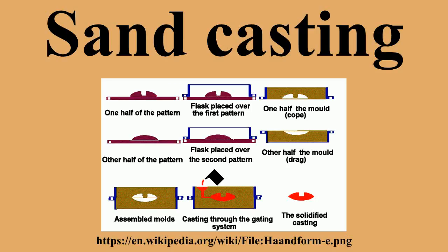In addition to the sand, a suitable bonding agent is mixed or occurs with the sand. The mixture is moistened, typically with water, but sometimes with other substances, to develop the strength and plasticity of the clay and to make the aggregate suitable for molding. The sand is typically contained in a system of frames. A mold box is known as a flask. The mold cavities and gate system are created by compacting the sand around models, or patterns, or carved directly into the sand.